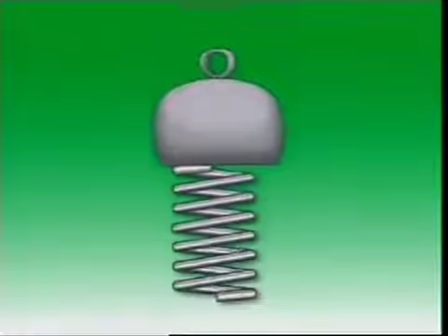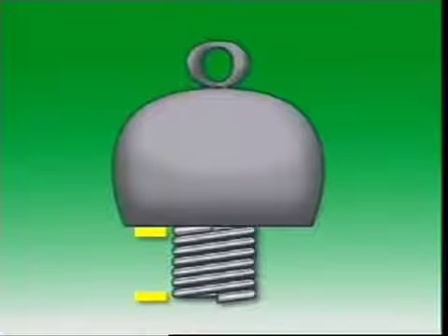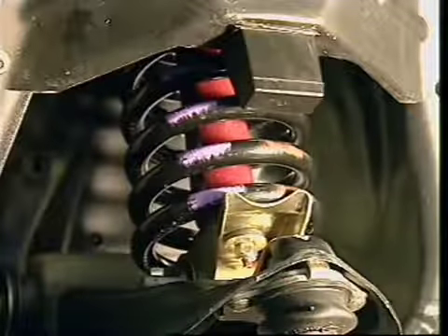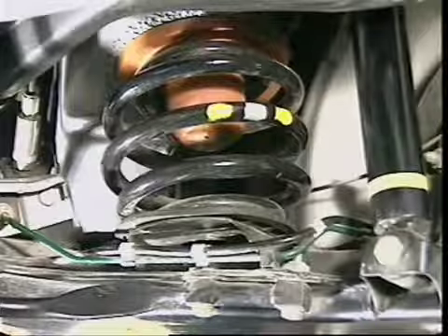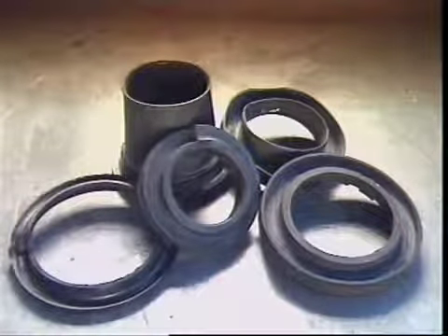As a cylindrical coil compresses, it can become coil-bound, which limits its travel. Coil springs can look alike but give very different load ratings, which are often color-coded for identification. They normally use rubber pads to prevent transmission of noise and vibration.